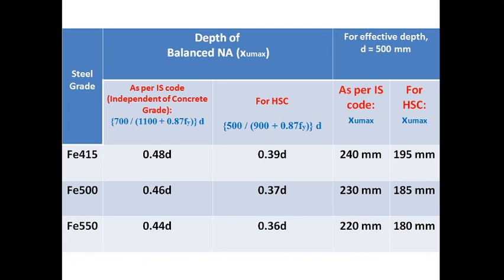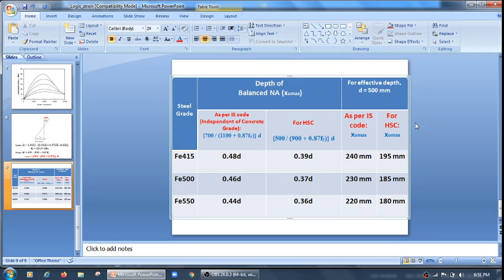So we should know the interaction between steel and concrete. Coming to a conclusion is very difficult, but I wanted to provoke a thought that instead of considering 0.0035 for all the grades, it is better to consider the failure strain as lower than 0.0035 as the strength of concrete goes on increasing. Thank you.